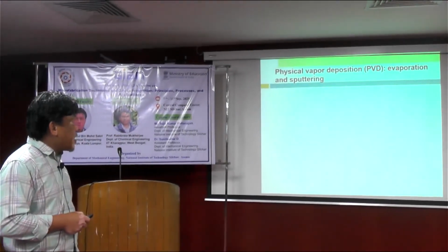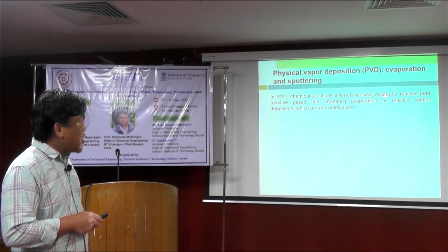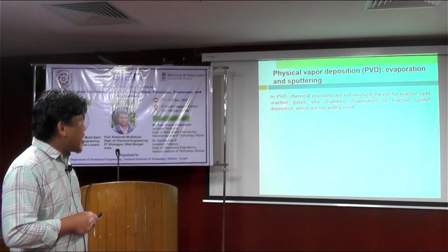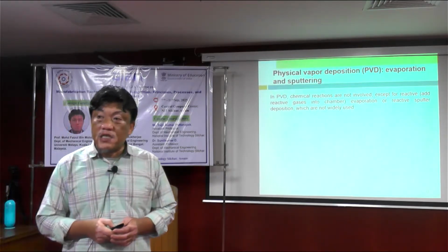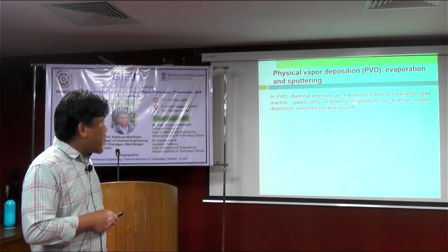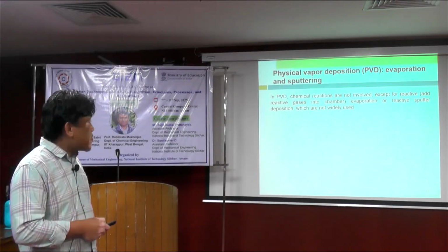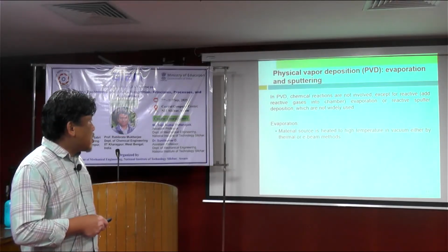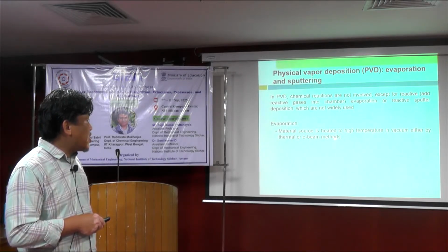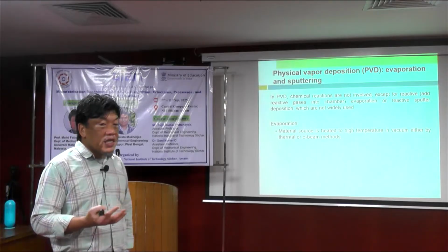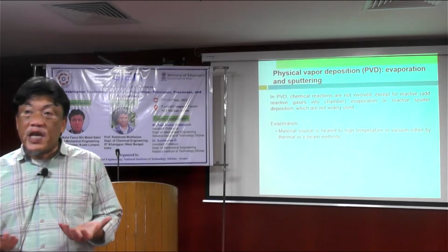So what is PVD? In PVD, chemical reactions are not involved, except for reactive deposition, where we add reactive gases into the chamber. We add some gas, but it's not really a chemical reaction like in CVD. But evaporation or reactive sputter deposition are not widely used. In evaporation, the material source is heated to high temperature in vacuum, either by thermal or E-beam method. Basically, you heat up something until it evaporates. So that is evaporation.